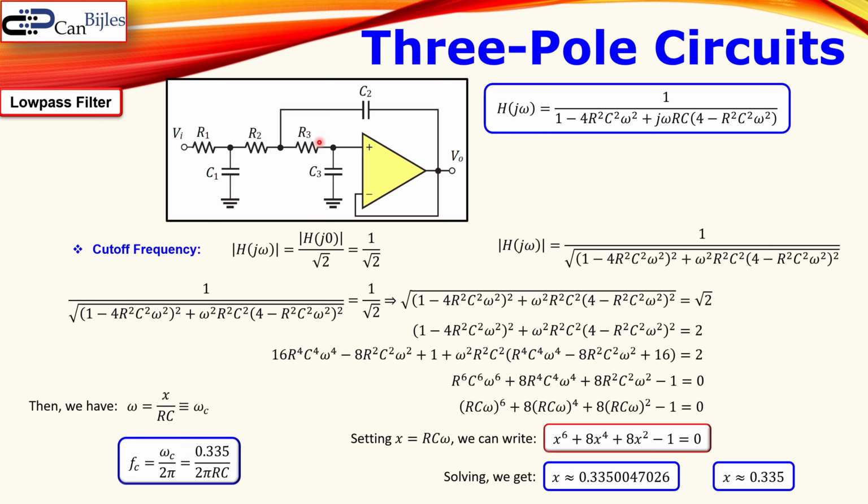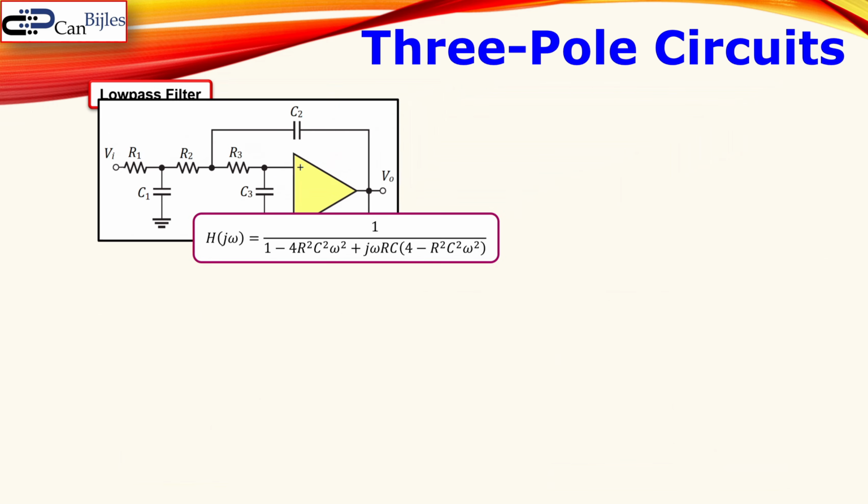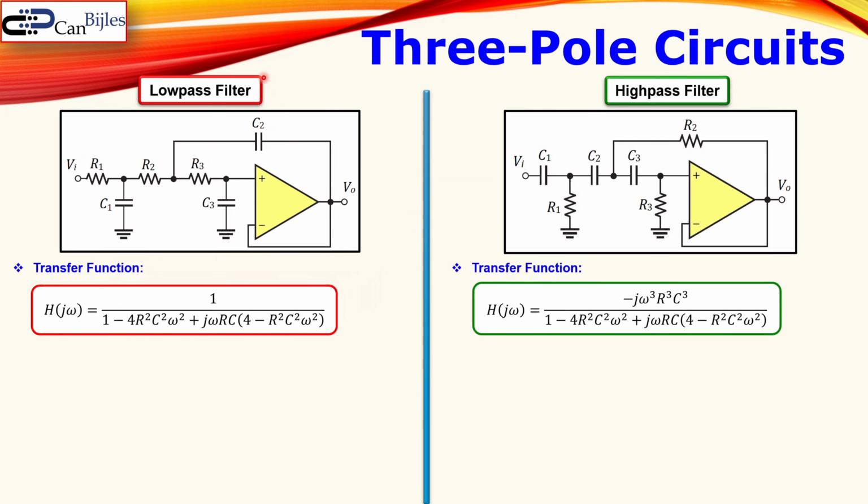You cannot just look at the circuit and say, oh, that's of course 0.335. You need to do that really step by step, carefully. Now we again collect the circuit here, left side and right-hand side. So left side low pass, right side high pass, transfer functions, and we see here again the cutoff frequency, or the minus 3 dB point, which is determined, and also in hertz.